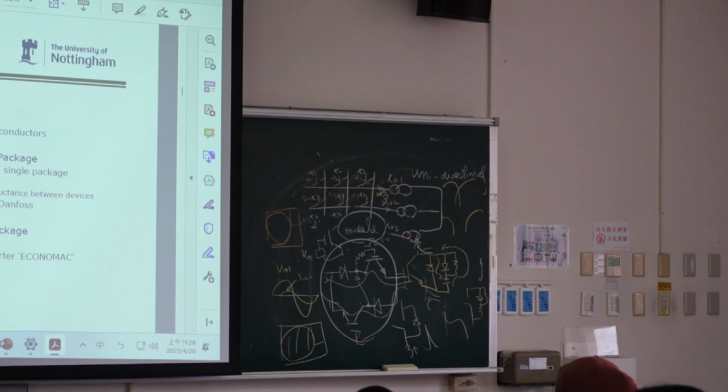In this package we have 2 IGBTs and 2 diodes, so it is equal to 1 AC switch. There is one company, Dynex Semiconductor, that is available to sell you an AC switch, 200 ampere. So you can buy it. This is good news.